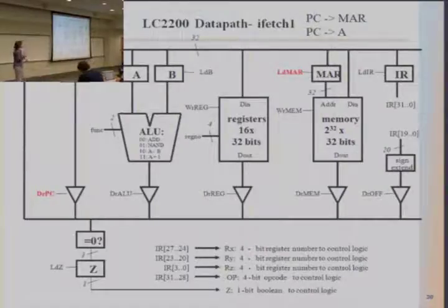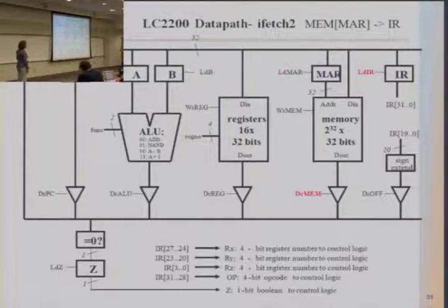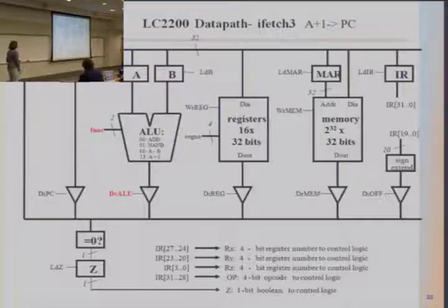If I don't do it this way, if I go here and write PC into MAR, and then address whatever is in memory and store that into the instruction register, then I would have to store PC first into A, then increment A plus 1 and store it into PC. Basically, those are just the steps for addition.